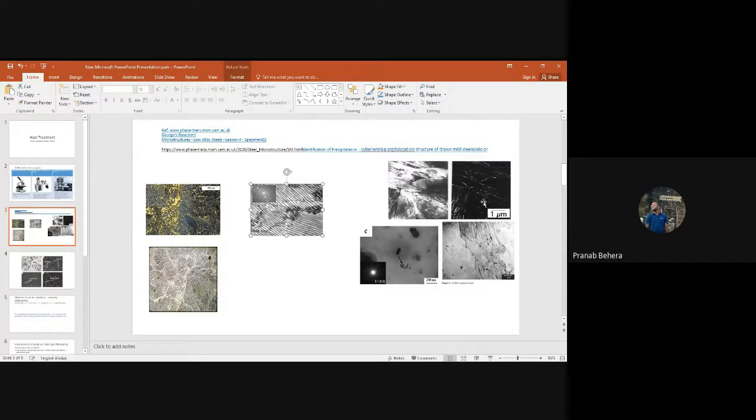Okay, these are images from a transmission electron microscope. So these are martensitic plates, or laths of martensite, not plate exactly. A plate, you can say, because if you really look into the three-dimensional structure of bainite or martensite or Widmanstätten ferrite, they are plate shaped. They are plate shaped basically.